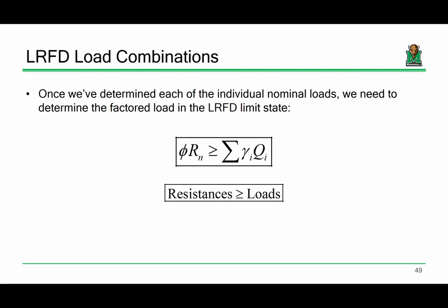And I can estimate that pretty easily. But live loads are a lot less certain. When we leave this room, there's going to be a whole other classroom that comes in here, and they're going to have different weights and different loads, and there's going to be different live loads in this room all day, right? So it stands to reason that if live loads have more uncertainty and you're trying to develop a design philosophy where you're trying to ensure uniform safety, well, the load factors need to be different. The multipliers for live loads need to be different from dead loads. And particularly, more often than not, they need to be higher.